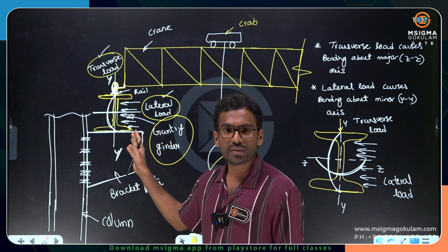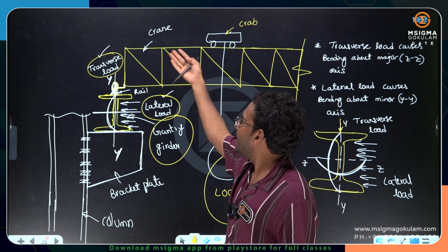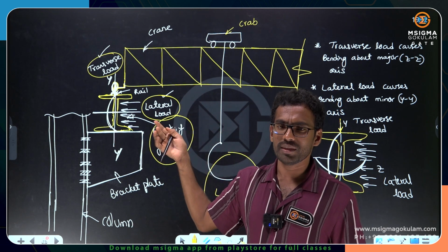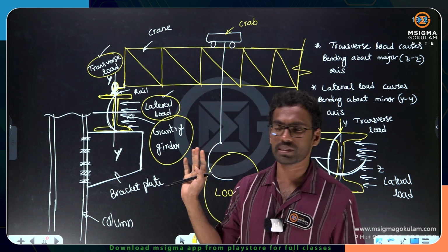Wind load, do you consider wind load for gantry girder? No, not at all, because when compared to these loads which are heavy loads, that wind load is very small, and inside the structures we are having this kind of things.